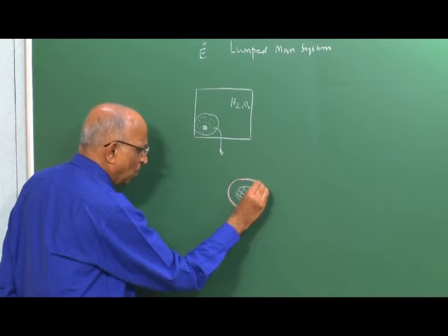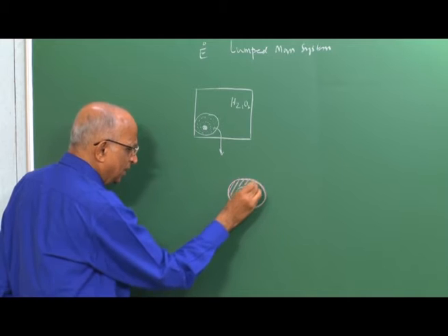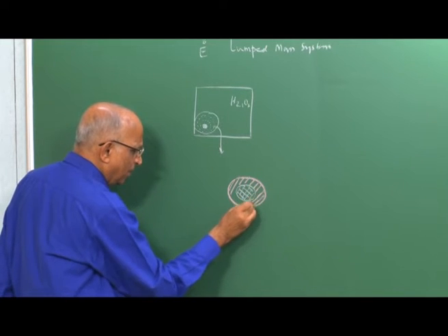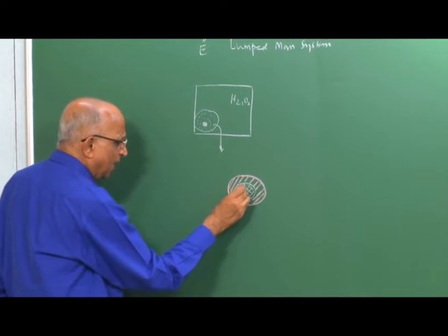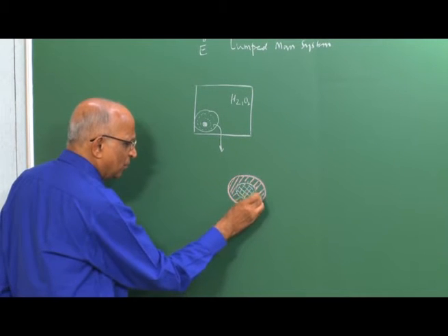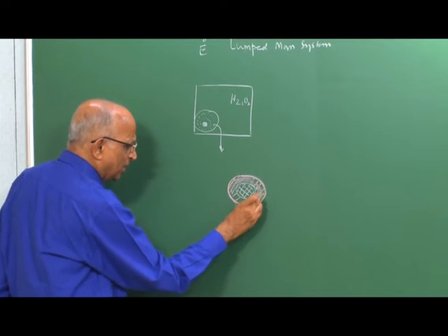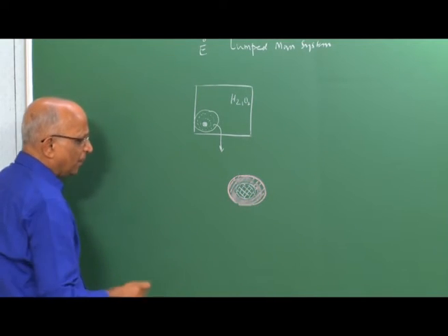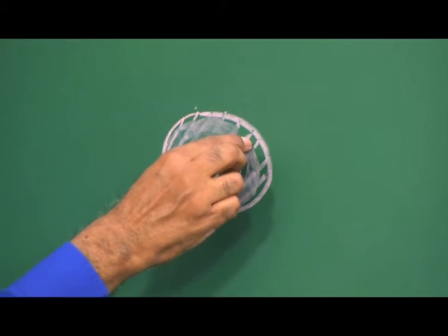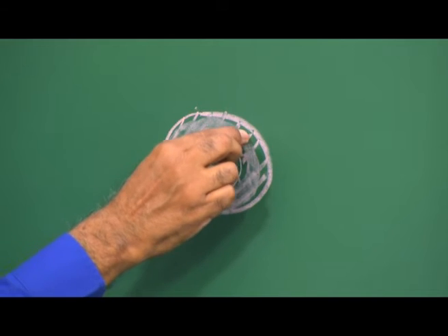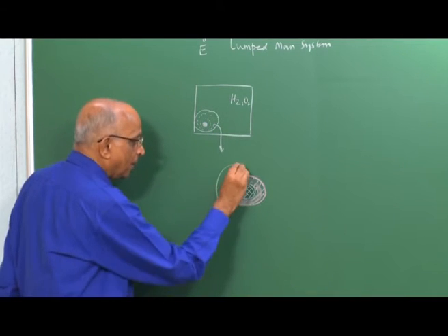That means, in a zone which I show in pink over here, the neighboring gas gets heated by the chemical reactions and heat generated in this small volume, and the heat diffuses out, the concentration diffuses out, causing a chemical reaction in the adjacent layer. And now what further happens? This adjacent layer, which is hot and undergoes chemical reactions, heats up the next layer.